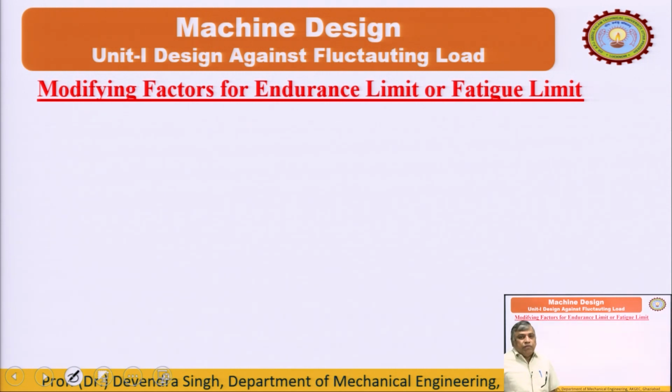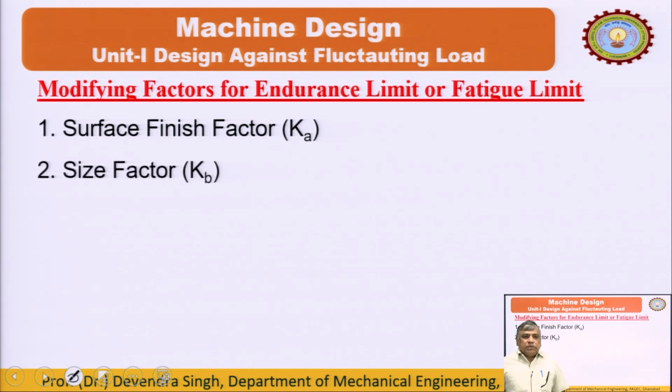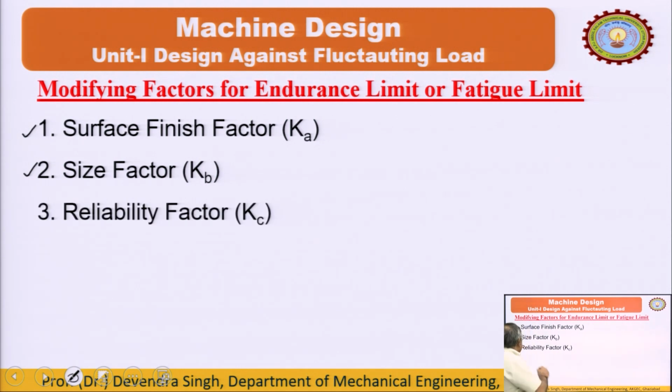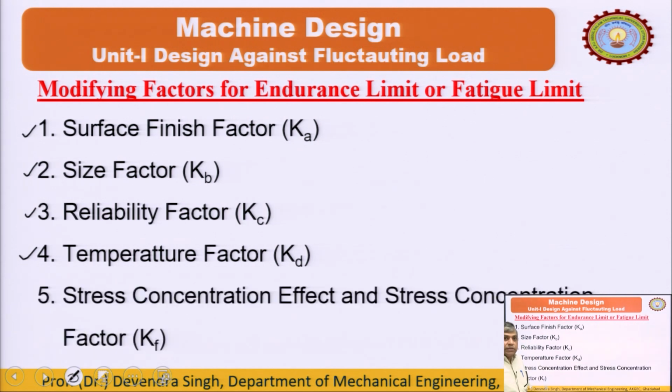So, the modifying factors, there are a number of modifying factors, but for academic purpose we will discuss the surface finish factor. What is the surface finish factor? Then we will discuss the size factor, then the reliability factor, then the temperature factor, then the stress concentration effect and the stress concentration factor Kf.